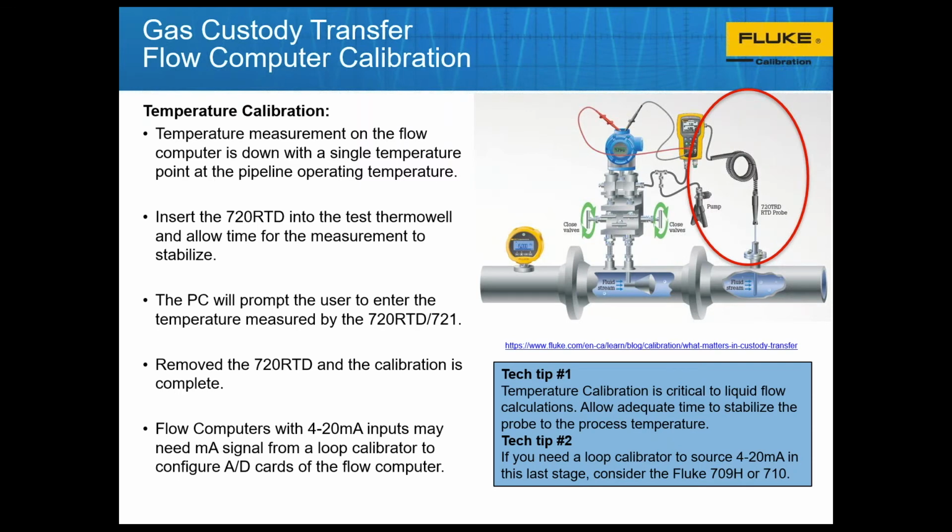And the reason you would be mostly concerned about making accurate temperature measurements is that it directly ties to volume. The volume of this material is very, very closely tied to the overall temperature. If you've pumped gas at a gas pump, you'll notice that it is calibrated to a specific temperature, and as the temperature changes, it changes its calibration for how much fuel you're buying. That's the same kind of thing that's happening with these custody transfers.